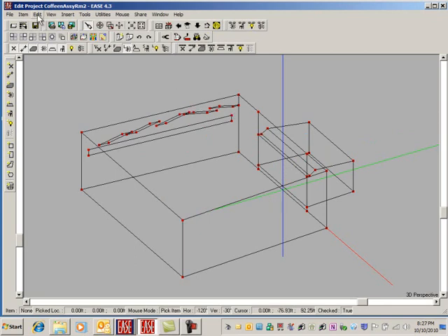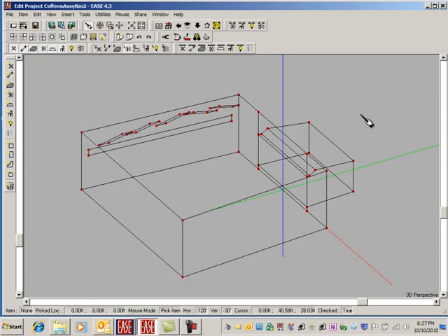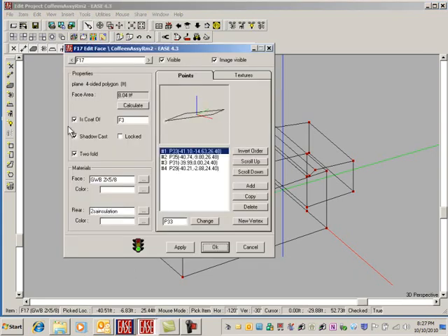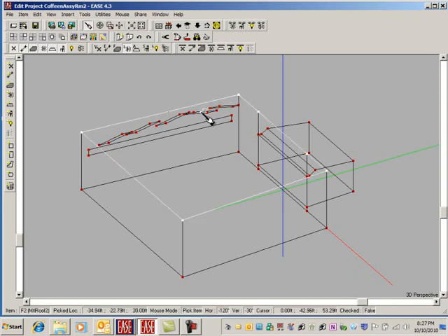When we delete them all, as you know, I just do this without any script and without any rehearsal. So these kind of things can happen. We'll do them again. It won't take us very long. And now we have a bunch of vertices which we don't want. We can get rid of all of these unattached vertices in one go by going to Tools and delete unattached vertices, and they're gone.